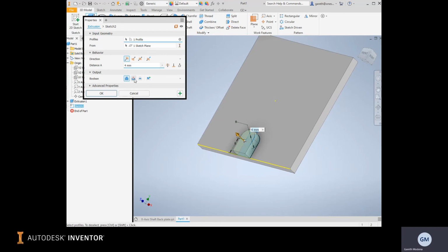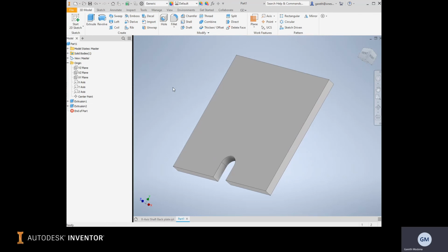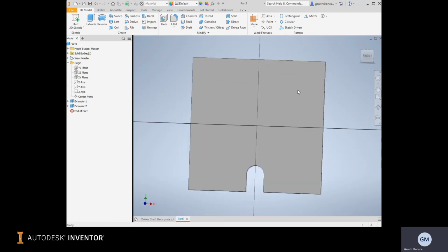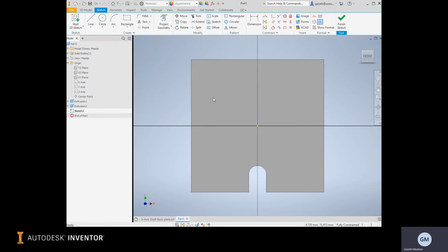The option is to actually just use the cut tool. We'll go into more details of the other options available to extrude in other segments of our YouTube series. I'm going to say OK to accept that. And if we want to do something like holes, we had the plate with 3 holes orientated around there. We're going to select the face we want to work with, click the sketch tool. It creates a new sketch for us to work on.